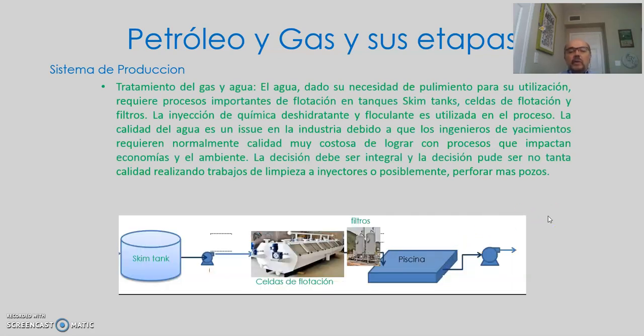After the feed water knockout separates most of the water, that water still has some oil in it. Like I said, in this particular field that I already mentioned, the water used to leave the feed water knockout with 2,000 parts per million of oil.